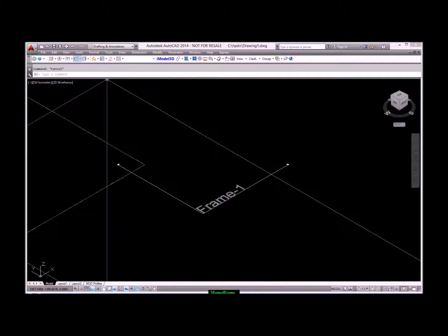Before getting into details, you need to familiarize yourself with some terminology used in the Model 3D environment. Please pay attention to the command prompt. Girder element: for concrete it represents a continuous beam while beam element represents a simple concrete beam. For steel, both girder and beam elements represent a steel beam. When modeling a frame, a girder element automatically generates beam elements between column elements. These beams will be hidden but will be used later in the analysis.